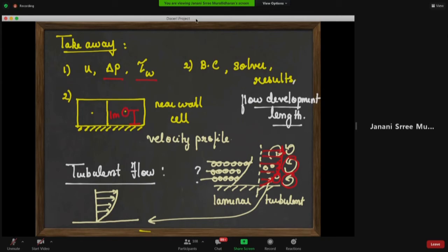But you're basically going to solve the Navier-Stokes equation only at the first cell center. So there is a huge unknown gap if I take 1 meter from a no-slip boundary condition to that cell center value. Okay, so I have no understanding of how this velocity can change.